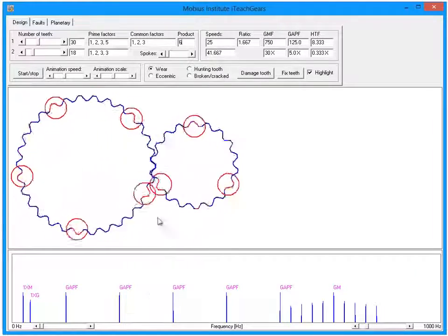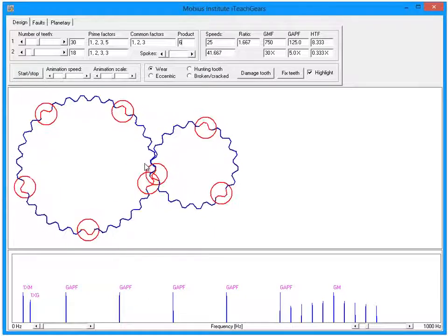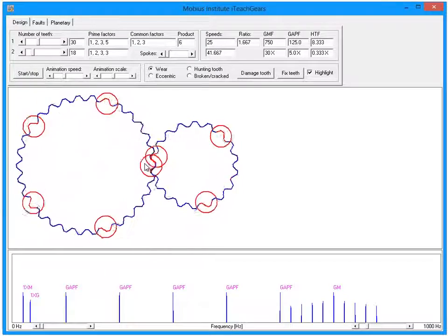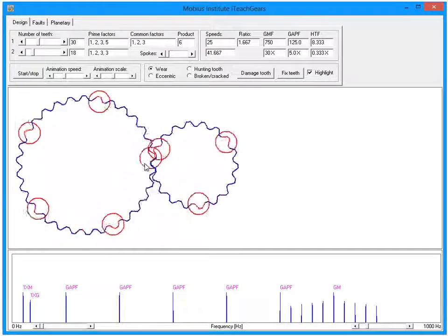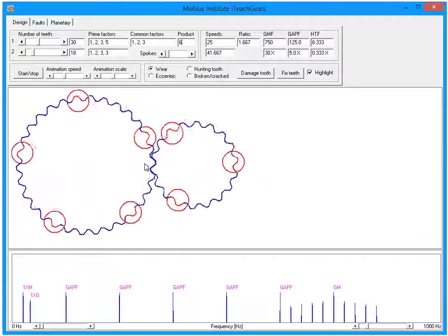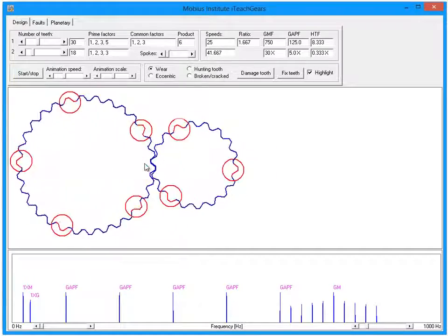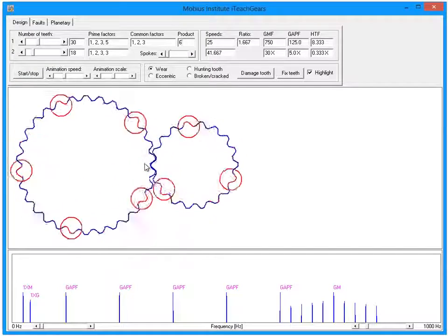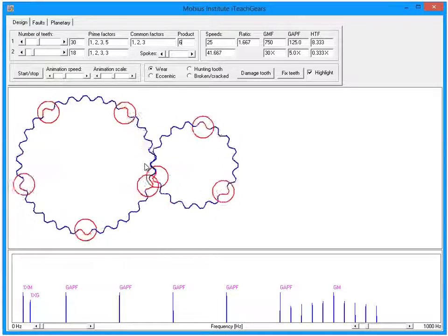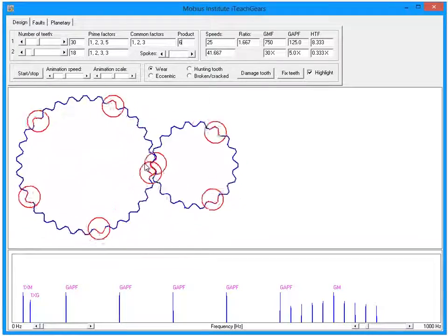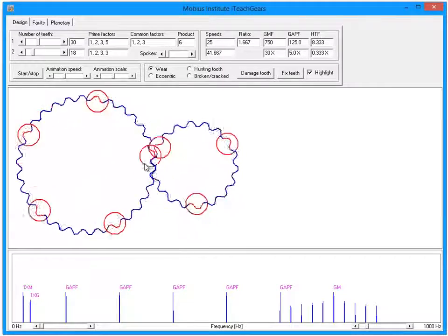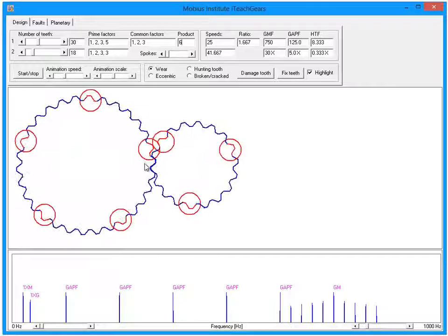And if we have any fault conditions which can excite that natural frequency, any impacting sort of faults with damaged teeth, then that natural frequency will be excited with a higher level of force, if you like, and therefore that peak can rise. We can also see modulation in that vibration. Instead of it being a solid impact, if the force of that impact rises and falls, then our gear natural frequency may also have sidebands.